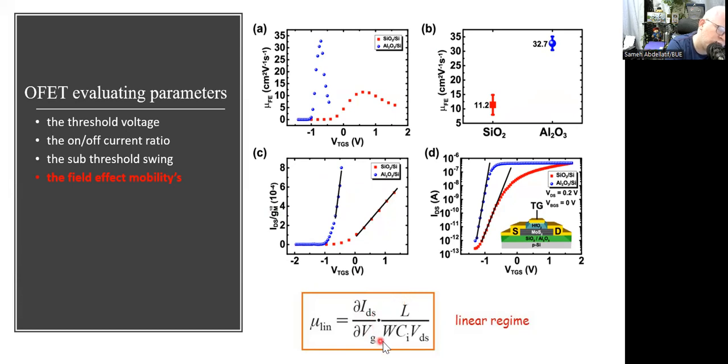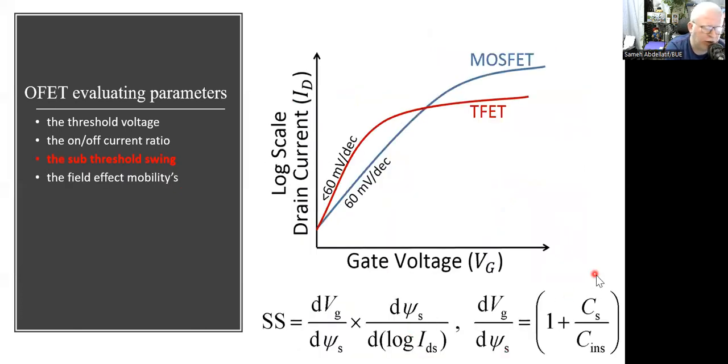However, there's also a constant of proportionality that is a function of the dimensions and the biasing VDS, because here you are using a transfer characteristic, ID versus VGS. So you have to have a fixed VDS for this operation. And also there is a capacitance term here. And also, if you recognize, there is also a capacitance term here.